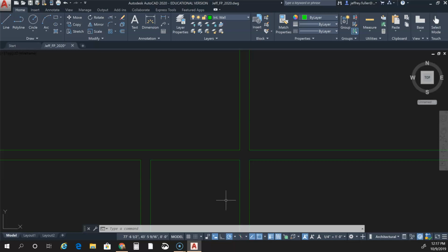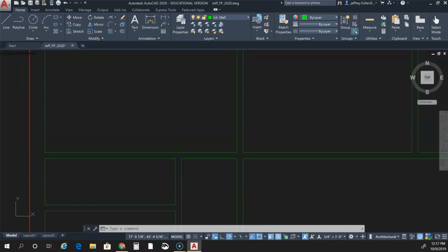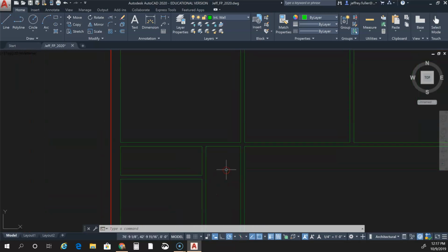It's called a door schedule. That door schedule will have all the different types of doors and all their measurements and everything else. And this door symbol that I'm going to put in here, that tag on it is going to link it back to that type of door. So the builders will know how big to make that hole and everything else based on that door schedule. It'll have rough-in sizes and things like that, which is probably foreign to you, but we'll talk about that.